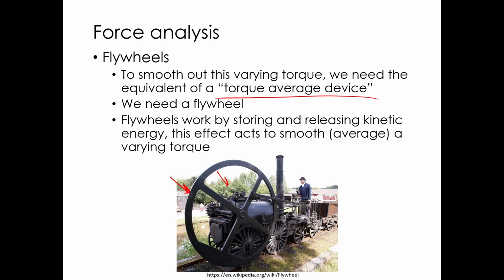So there's a lot of functions, but its biggest one, and the reason it's so big and heavy, is because it's a flywheel for the engine. It'd be fun to try to run one of those without that. You'd have to rig up a separate ignition system for it and cooling, but I've never tried that. And again, if it even runs at all, it's going to run very jerkily.